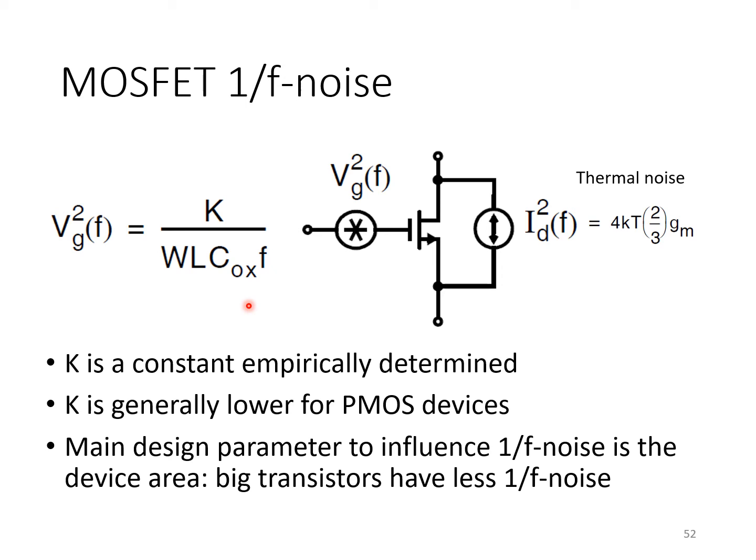And this in a sense is convenient because if we have an amplifier whose DC performance we really, really care about, that is, we're using it mostly for very low frequency or DC signals, then we might not mind using large transistors. The associated parasitic capacitances presumably may not cause us too much trouble if we're dealing with very low frequency signals.